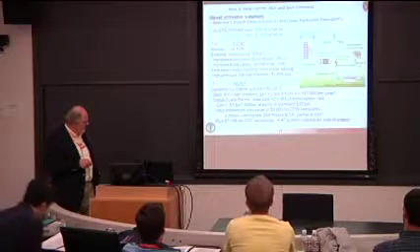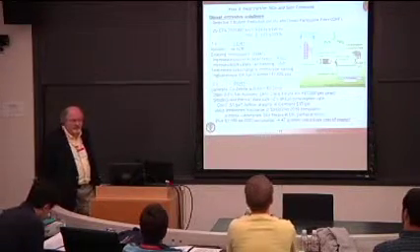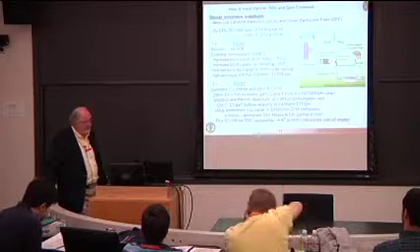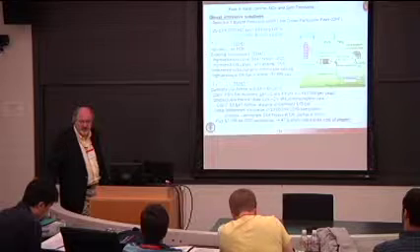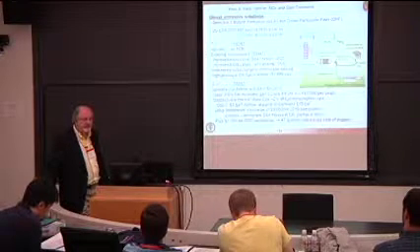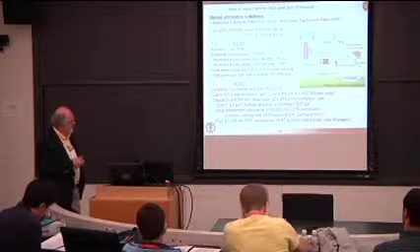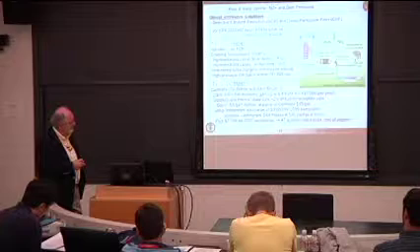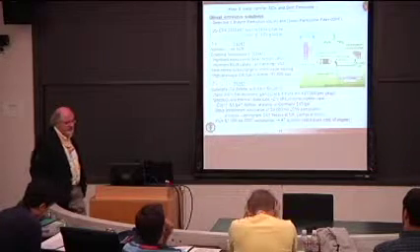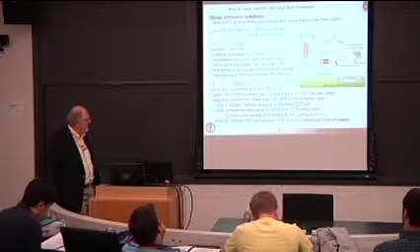The other thing that Volvo has pointed out is that it already cost them $7,000 extra for an engine to meet the 2007 emissions, and that was adding the DPF, because that diesel particulate filter fills up with soot, and you have to burn off that soot occasionally through what's called a regeneration cycle. So you spray fuel into the exhaust to heat up the filter to burn off the collected soot.